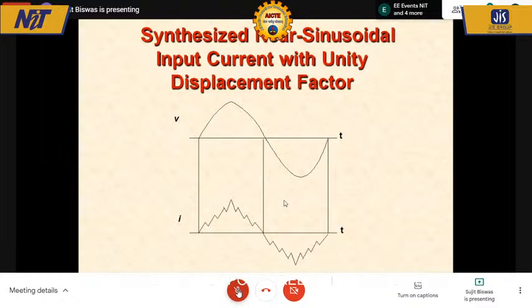So what we want to do in the converter is that we should be able to look at the sinusoidal voltage because the supply voltage is reasonably sinusoidal most of the time, practically with less than about 3% total harmonic distortion. That's good enough. And we want to create a synthesized current for the converters, where the current should be more or less shaped like this, with zero crossings coinciding.